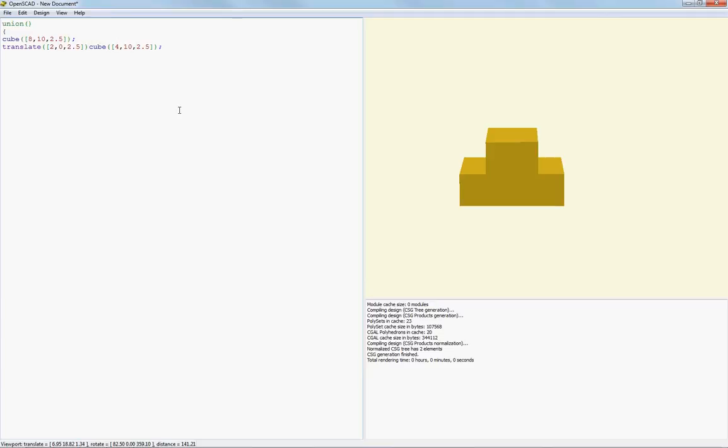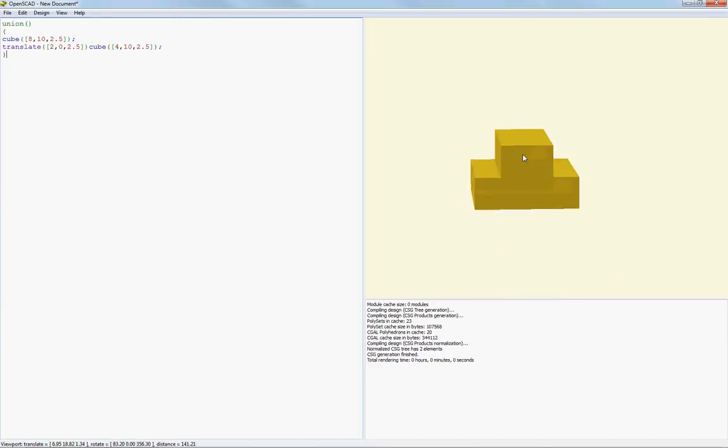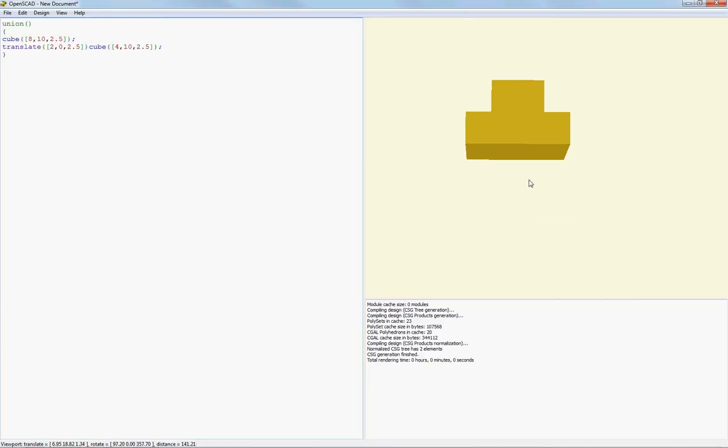No worrying about doing multiple operations to the same thing, because you're going to modify this entire object anyway. You're going to want to drill a hole, which we're going to use the cylinder command for. So you don't really want to muck around with it too much. The union just saves you a difference or two.